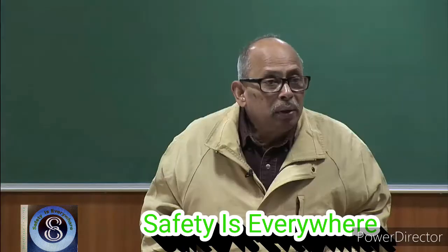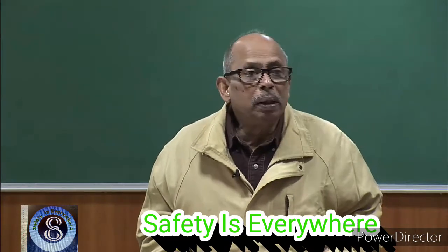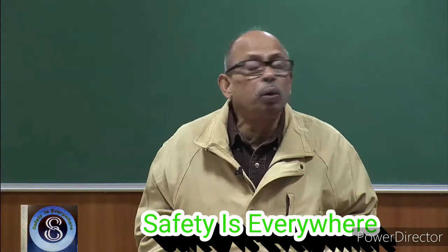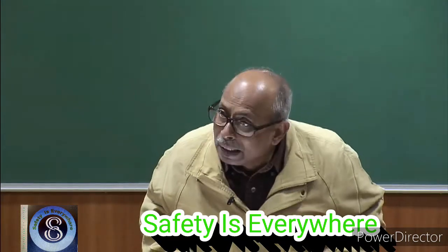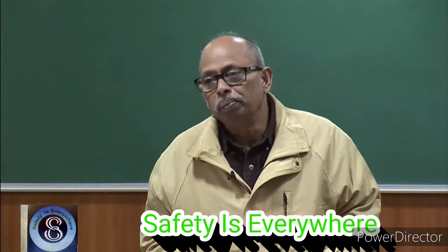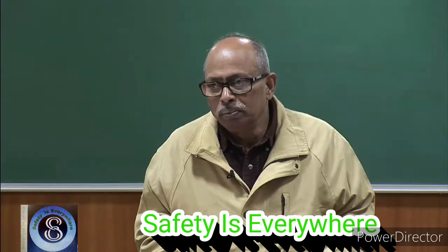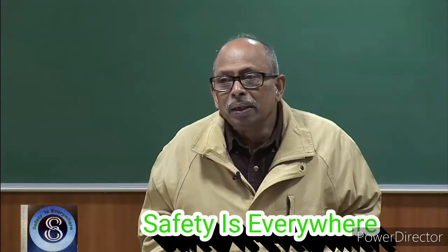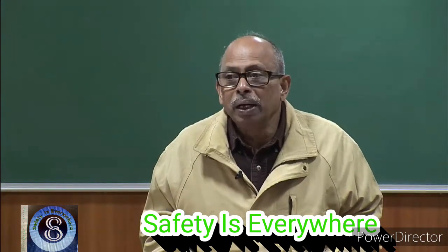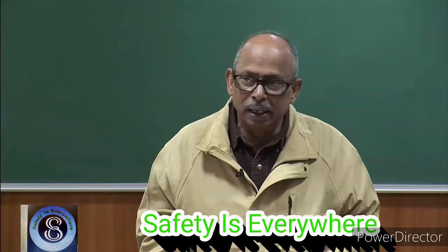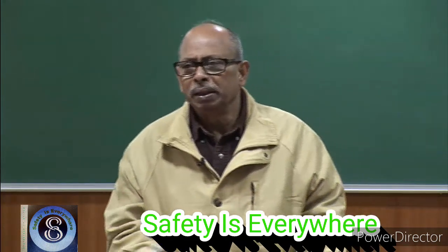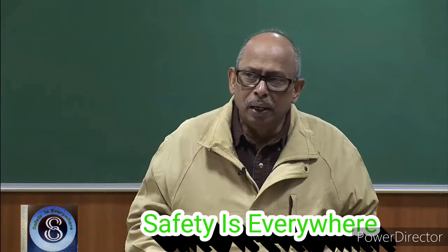Now, what is fire load? Fire load is, you can identify total quantity of combustible material in the room divided by the area, floor area or internal surface area. People use both, but generally it is floor area.